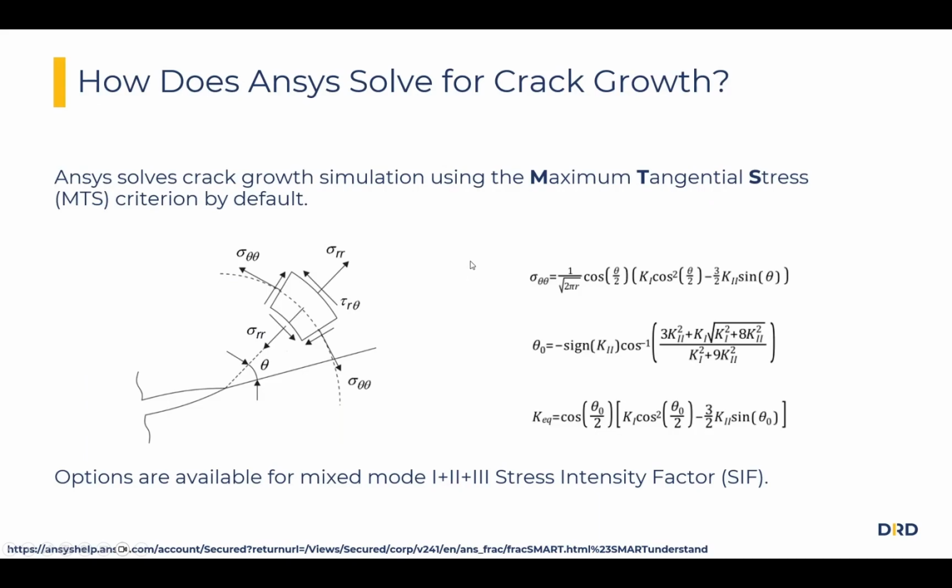Now again, Ansys simulates crack growth through a couple different means here. Ansys will calculate the far field stresses around the crack, determine the direction of crack growth, so we can have general 3D crack growth that is not planar.